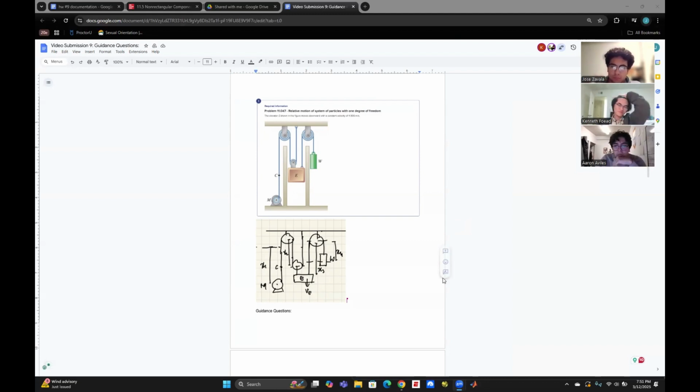Yeah. I'd like to add a little bit to that one. I honestly think that for that question, you don't have to solve any equations in order to do that at all, right? Because you can understand the heuristic of the work energy theorem, which is what this question is actually asking. That means that the work that's happening is the same. For E and W, there's a relationship of 1 to 1. So the mechanical advantage of the pulley system there is 1.